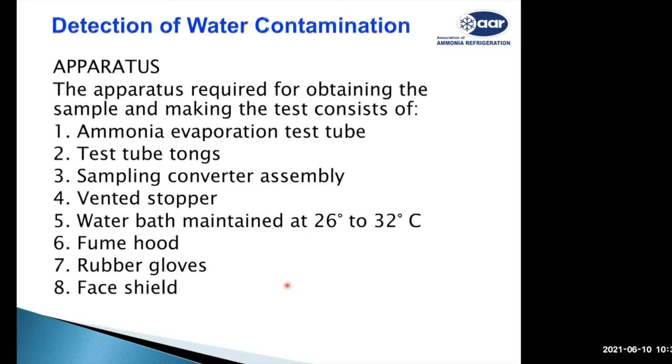One simple observation is to find out the suction pressure at which your compressor is running and the effective suction temperature you are getting. If it is operating at similar conditions, the possibility of water is less.